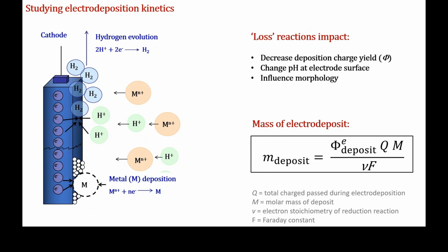Okay, so I've mentioned, or rather I tried to start showing why it's important to look at side reactions, right? We've seen that if we stick to the acidic pH in a normal nickel system without any complexing agents, we can expect some competition between the reduction of nickel and the reduction of protons or water to hydrogen.